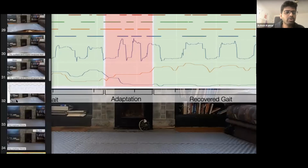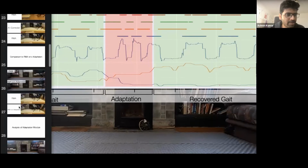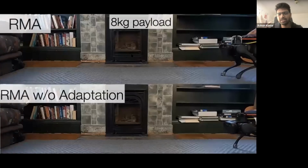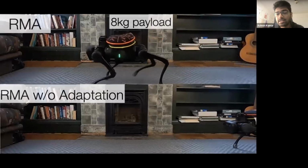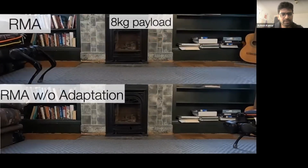And I think the true test lies in the method working. So we have a comparison where we just switch off the adaptation module. Everything is the same; we may run the adaptation module for the first time step and then freeze everything. Here, the top is with RMA and it's an 8 kg payload. This is roughly 70% of the body weight of the robot, and the recommended payload from the manufacturer is 3 kg.